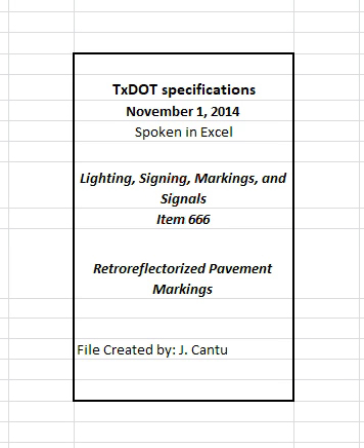5. Measurement. This item will be measured by the foot, by each word, symbol, or shape, or by any other unit shown on the plans. Each stripe will be measured separately. This is a plans quantity measurement item. The quantity to be paid is the quantity shown in the proposal unless modified by Article 9.2, Plans Quantity Measurement. Additional measurements or calculations will be made if adjustments of quantities are required.